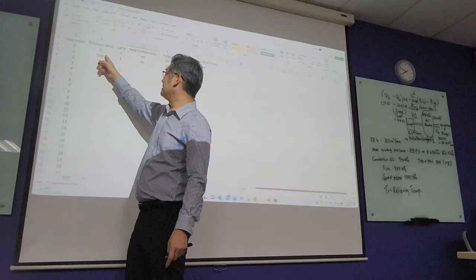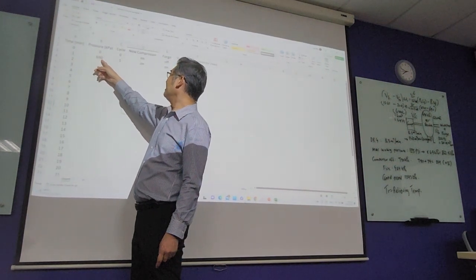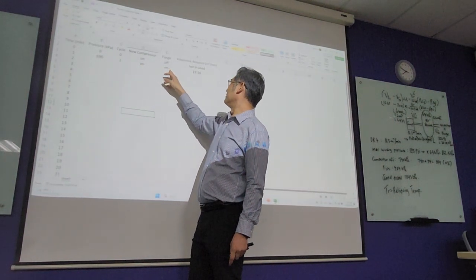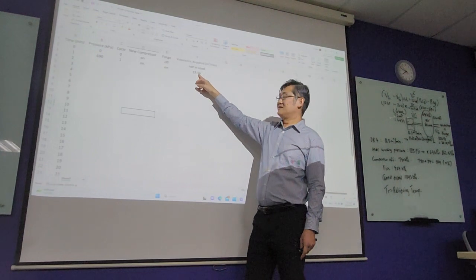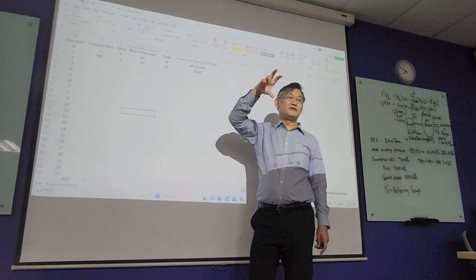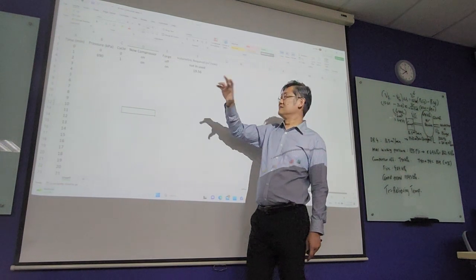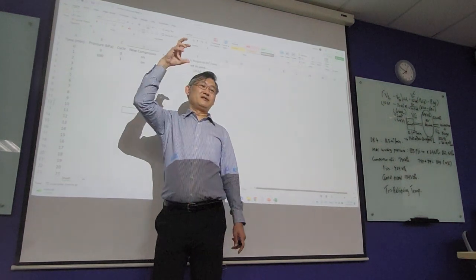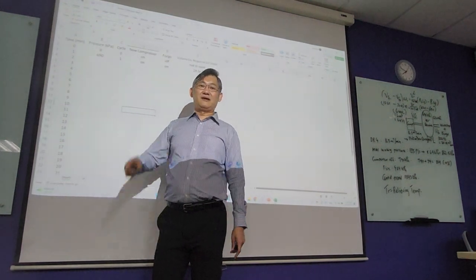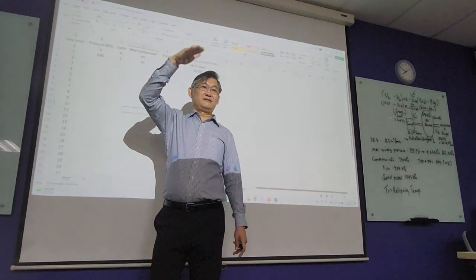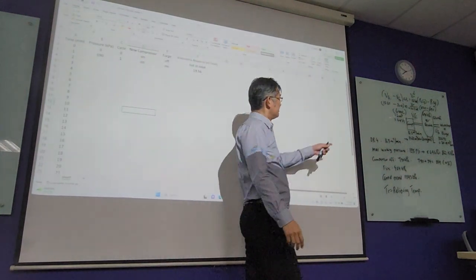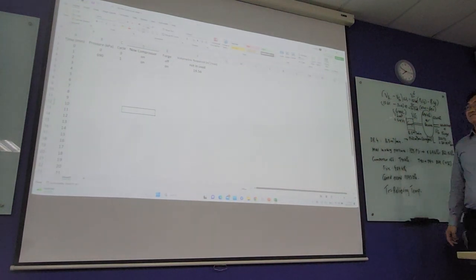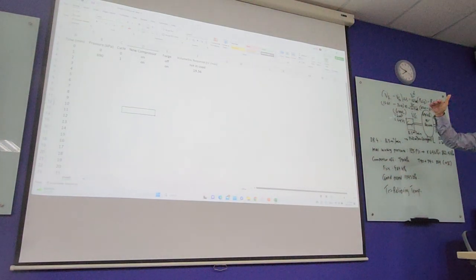And then over here you can see, given 690 initially, cycle number 1. Cycle 1 new compressor, force on. Volume required 19.56 because force operation is the maximum of the surge. So what you need to do is to calculate after 1 minute what will be the volume inside the tank. Another minute, you calculate again, by using the formula. So you list, and then you calculate.